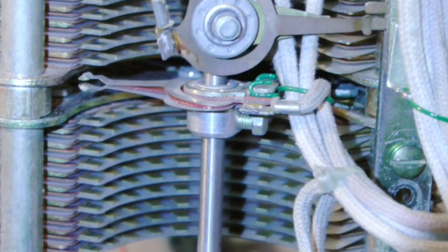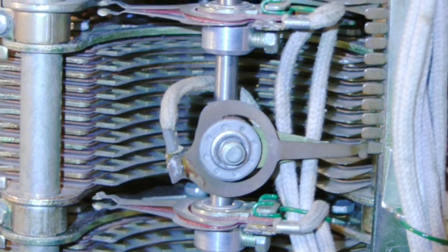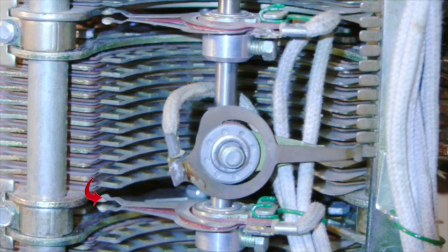Each wiper assembly has 2 wipers. In the wiper assembly for the lower bank tier, the top wiper is for the ring terminals and the bottom wiper is for the tip terminals. Similarly, for the middle bank tier, the top wiper is for the ring terminals and the bottom wiper is for the tip terminals. In the upper bank tier, the top wiper is for sleeve terminals for line circuits 100 to 199, and the bottom wiper is for the sleeve terminals of line circuits 00 to 99.